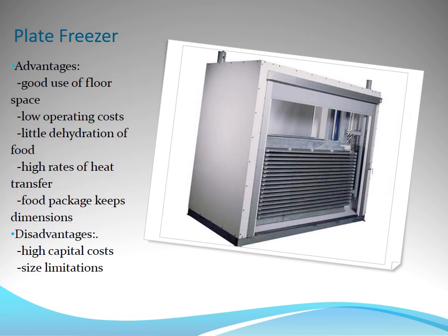Next one is plate freezing. In this method, food products are placed in contact with a cold surface. The metal surface is cooled using cold brine or vaporizing refrigerant. This process is suitable for packaged food products which may rest on, slide against, or be placed between cold metal plates. It is also suitable for unpacked foodstuffs. Examples: items which can be frozen by adhesion to a slowly rotating cold drum. Fruit juices can also be frozen in cylindrical scraped surface heat exchangers.